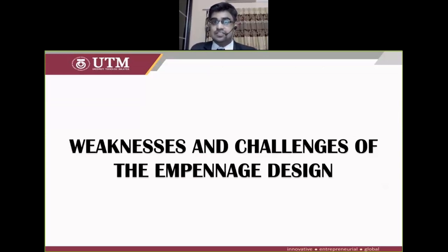In terms of weaknesses and challenges, the main factor contributing to the problem is environmental factors such as high wind flows. During this stage, the theoretical estimation is not accurate as the control surfaces are tossed by turbulence. This in turn will cause fatigue to occur on the structure, both stabilizers, horizontal and vertical, and the control surfaces, rudder and elevator respectively, that eventually affects the integrity of the structure and causes cracks and breakage of the structure.